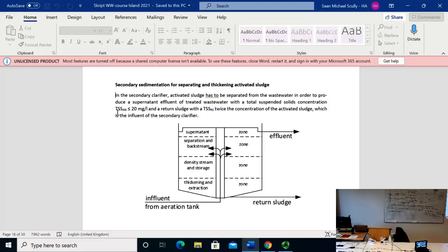So it has something to do with residence time, but also we know from sedimentation criteria the surface loading, as a hydraulic surface loading, and then obviously we need retention time in order to get the solids concentration, our return sludge. And there's also a bunch of empirical knowledge flown into this. I have done this. This is also in the text which I gave you.